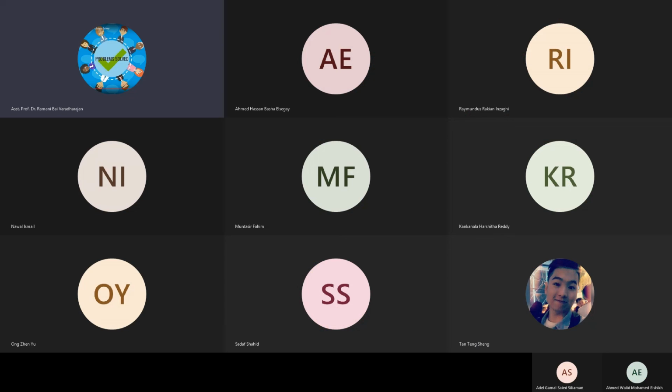We saw just now that the distribution of the loading should be uniform. Wherever there is a differential loading or asymmetric loading, you need to plan accordingly to redesign it. That is given by two different points. One is the point of rigidity and the other is the center of gravity, or otherwise called the center of mass.